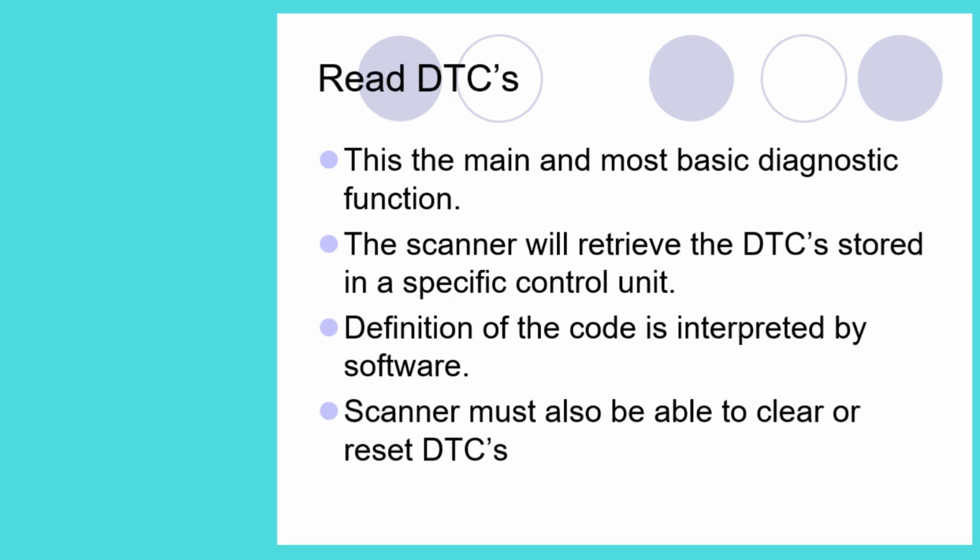To read diagnostic trouble codes. This is the main and most basic diagnostic function. The scanner will retrieve the DTCs stored in a specific control unit. The definition of the code is interpreted by the software. The scanner must also be able to clear or reset DTCs.